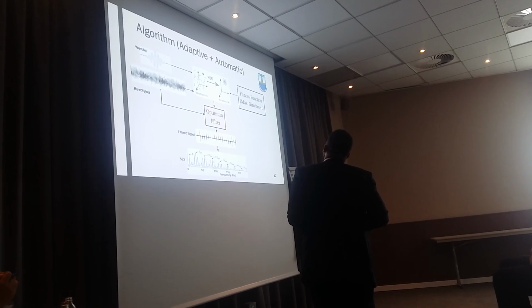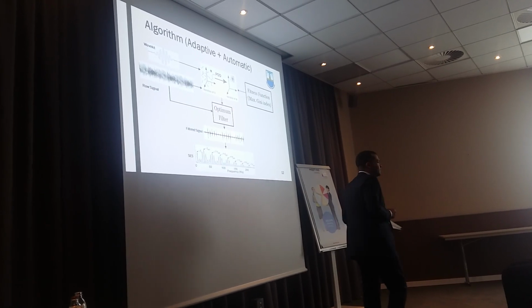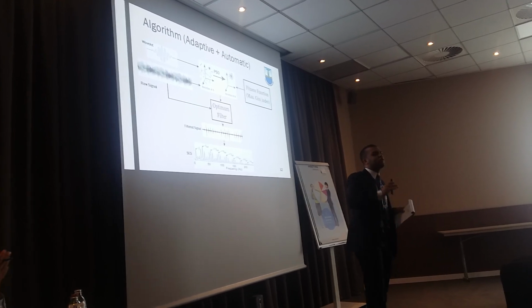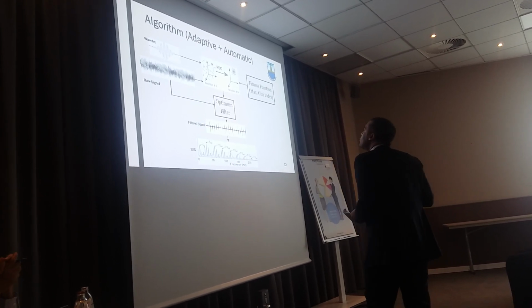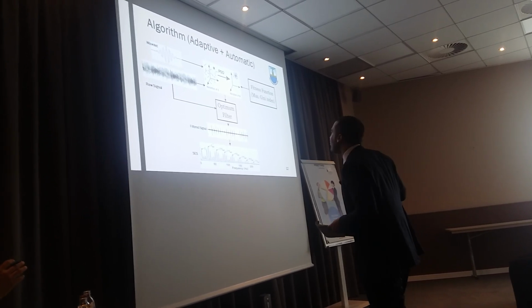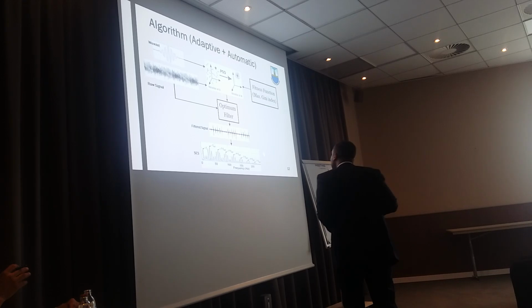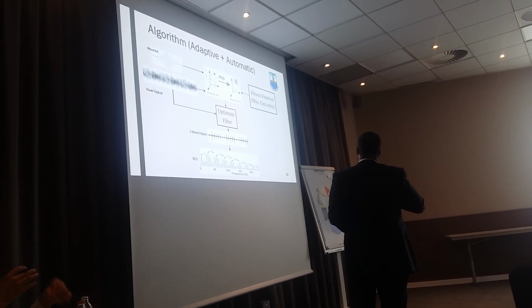And the fitness function is to maximize the Gini index of the filtered signal, namely the Gini index of the squared envelope of the filtered signal. The output of the optimization process is the optimum filter, which is a filter that produces a filtered signal with maximum Gini index, or in other words, maximum impulsiveness.